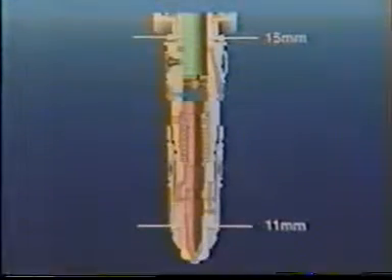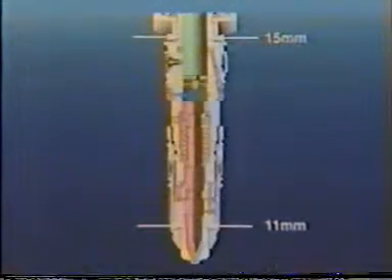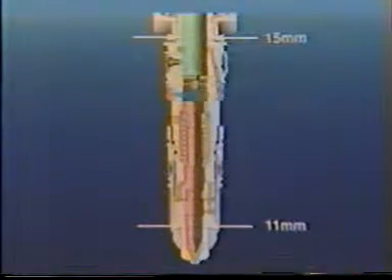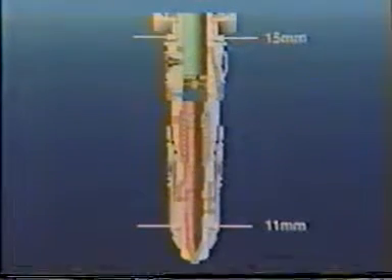The trapped fuel becomes a solid link and all three plungers move down together. As the lower plunger moves, the rail feed port is also closed. The timing and upper plungers have a diameter of 15 millimeters compared to the 11 millimeter diameter of the lower plunger.